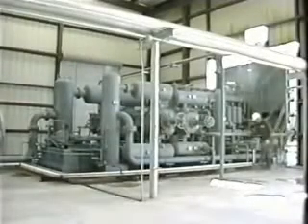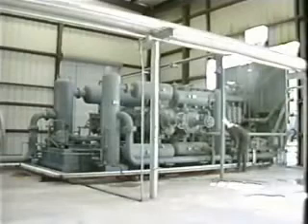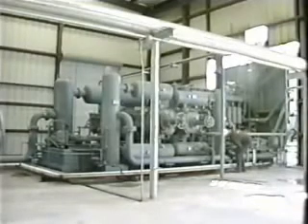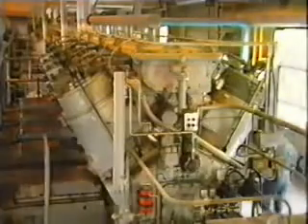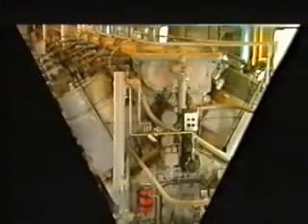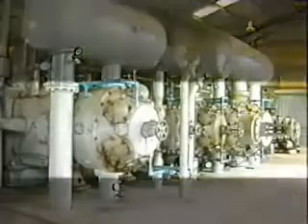Compressors come in different types to accommodate different compression requirements. Now let's take a look at the most common compressor types. In an integral unit, the prime mover and the compressor are combined, sharing the same frame and crankshaft. The power cylinders are usually vertical and the compression cylinders horizontal. In another design, a V configuration is used with the power cylinders on both banks and the compression cylinders on the horizontal.